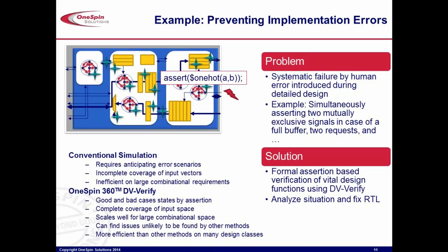A little bit on going a bit on the higher end. So obviously you can also have human failures that are introduced during the design phase, RTL bugs effectively, and in this case, to verify a vital part of the design, one can use assertions to express in a much more compact, much more powerful way what the specific critical expectation is.